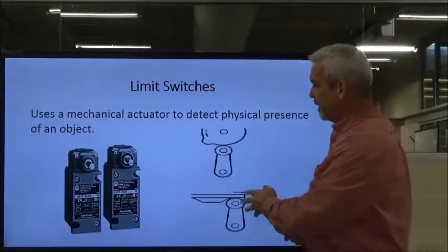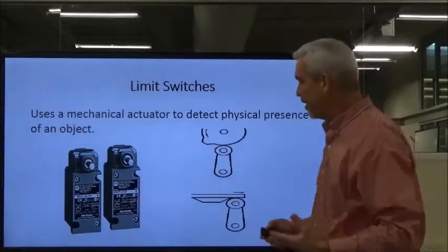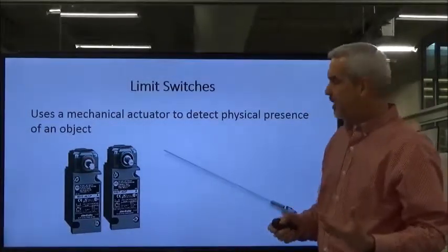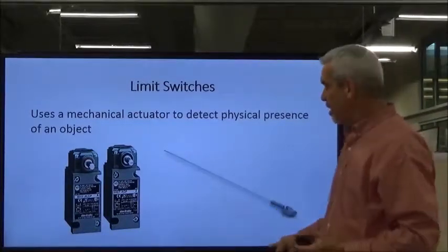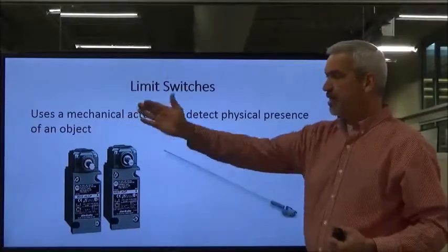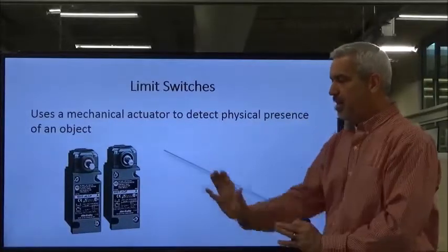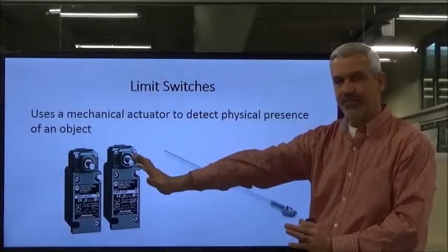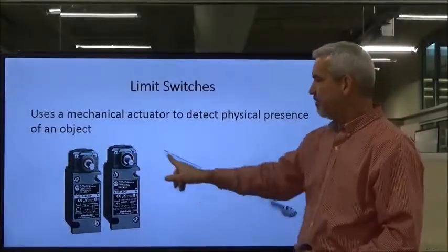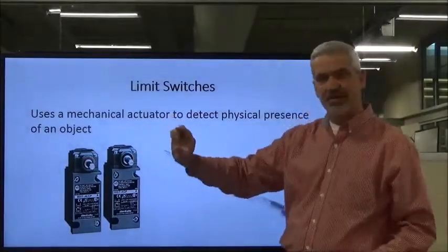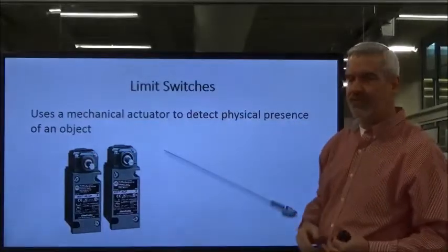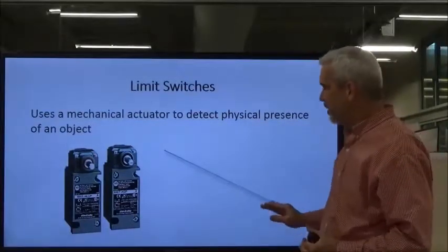The actuators, again, this is just one type, the one with the roller on it. There are a bunch of different types of actuators, too many to go into. This is one I picked up because I've worked with these before. These have long reach, so if you have a limit switch mounted here and a part coming out over here, a fairly good distance, the switch can reach it. The actuator I showed you earlier was about 1.5 inches from the shaft. This one will reach much further.